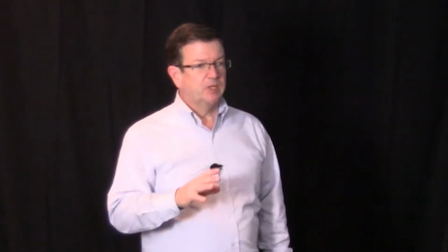And a per phase analysis, what that actually involves is you have a three-phase power system, and the assumption is the event on all three phases, the result of whatever it is you're modeling on all three phases, is the same. It's balanced. So a three-phase short circuit, you're considering that, well, whatever the current is, tens of thousands of amps, it will be the same on phase A, on phase B, and on phase C.